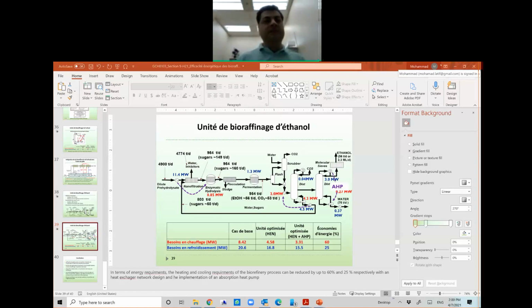You are saying that between process-to-process heat exchangers, you cannot have violation of the pinch point. Because, for example, when you talk about combustion, combustion is a utility. It's not process to process. So these are the things that we have to be clear.